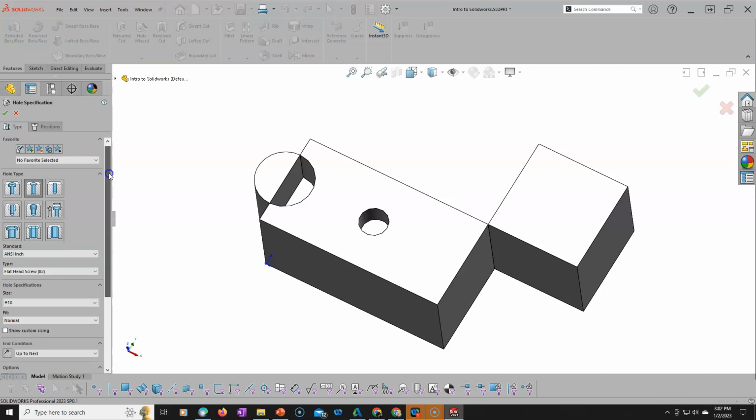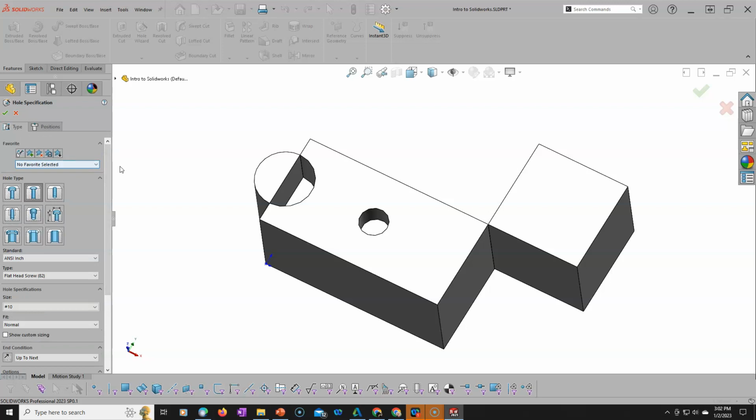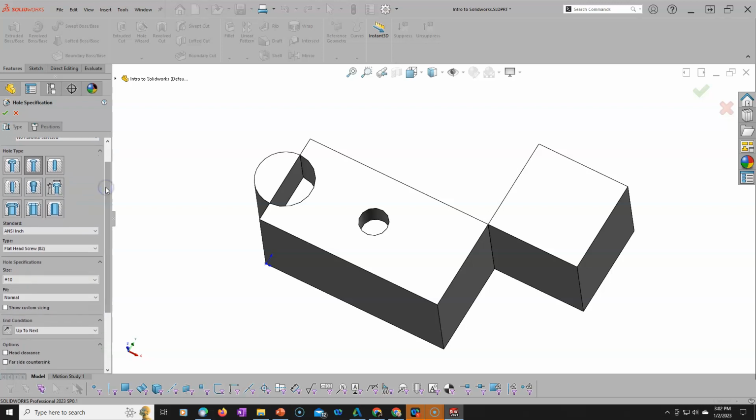And the first is going to be the hole type, and if we've set a favorite or a combination or some modification series, then we'll do that. That also reminds me of something else I forgot to do, but we'll go back one thing at a time. The counterbore, the countersink, the hole is the standard geometry, and tapped holes, a pipe tap or tapered pipe tap.